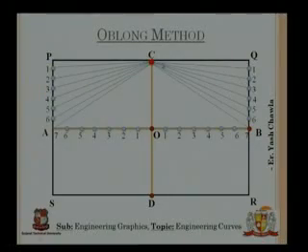Now I have taken this point because this point will be there on the ellipse, so I marked it as red. Now D to 1 and then extend it to meet C1. D to 2, extend it to meet C2. D to 3, then extend it to meet C3. This is how we are going to do.